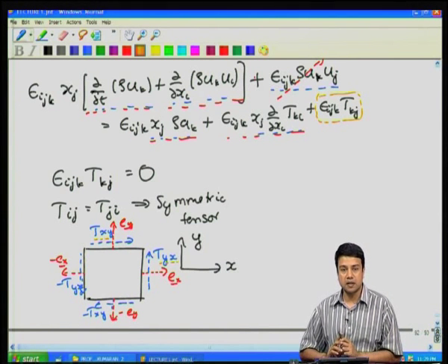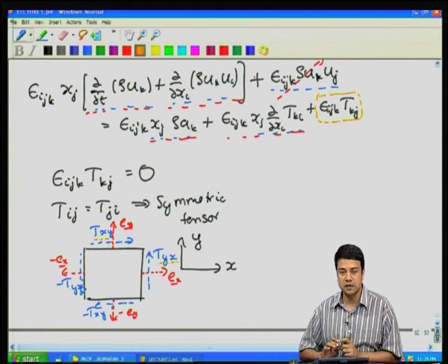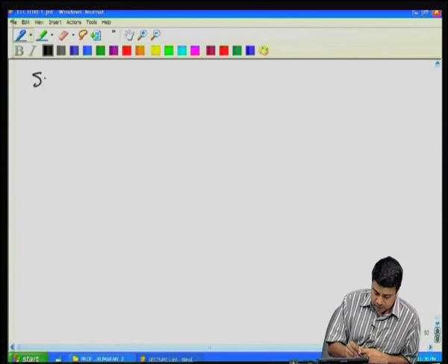That is the important implication of the stress tensor being symmetric, and that is why typically in textbooks you will see the shear stresses written in this fashion without any rotation. And that is because from angular momentum conservation, there is no net torque on the system, there is no microscopic torque on the system. The net torque on any differential volume has to be exactly balanced. Otherwise, you will violate angular momentum conservation. And this net torque is balanced if the stress tensor is symmetric. So, now let us look at the stress tensor.